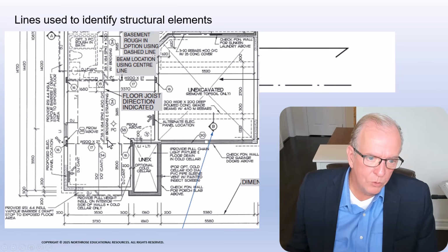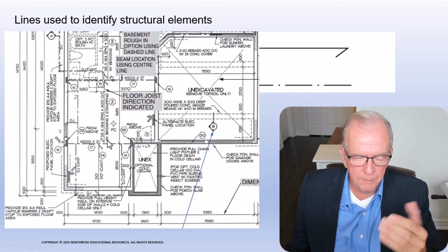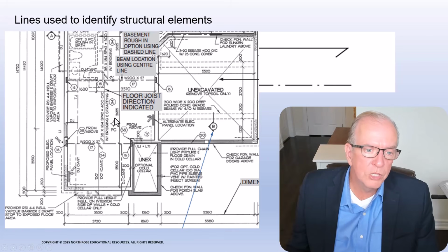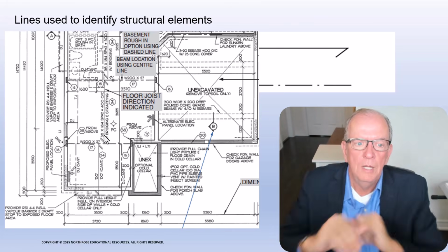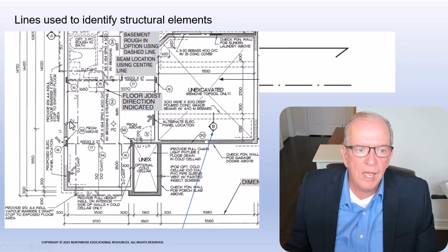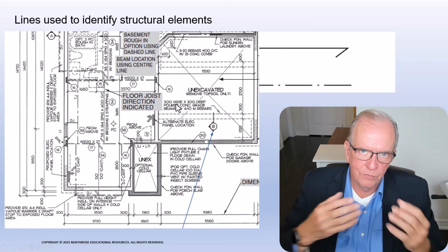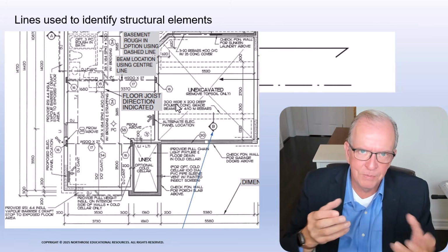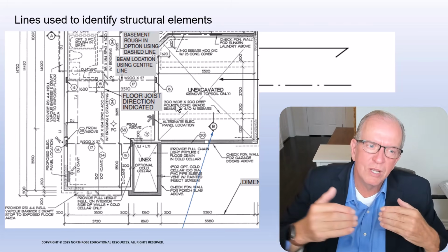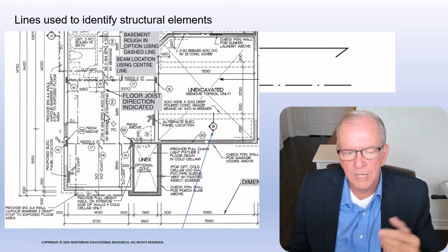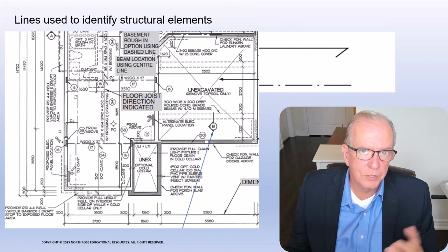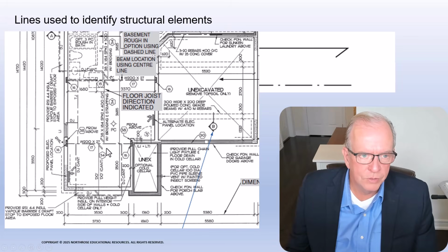And then it says W, and we'll talk about abbreviations in one of the upcoming videos, which is in chapter 4, with bridging and strapping. That just means there's going to be bridging, usually cross bridging. That really strengthens the floor. And in this case, because it's probably a pretty long span, it's going to have strapping. So in our building code, if you put strapping, and you only find that usually in a basement situation, it allows you to stretch out a little bit further with the materials. Of course, in an alternative situation, another set of drawings that I have with the book, The Brace Side, we use basically an engineered floor system. And we'll talk about that again in other videos.